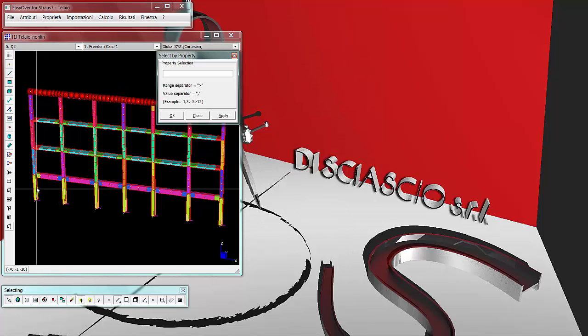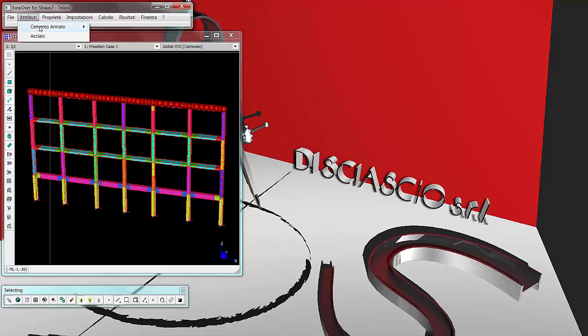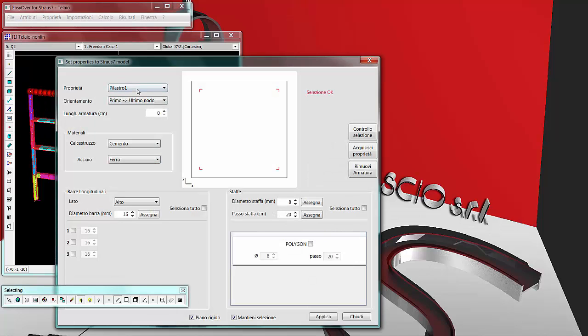Now let's see the example in question, relating to an existing building. We apply a property reinforcement defined for the columns. It is necessary to define the length of the portion to be reinforced, e.g. 80 cm, and check the bars and stirrups of the property that you actually want to insert in the element, with the relative sizes, bar diameters and spacing of stirrups.